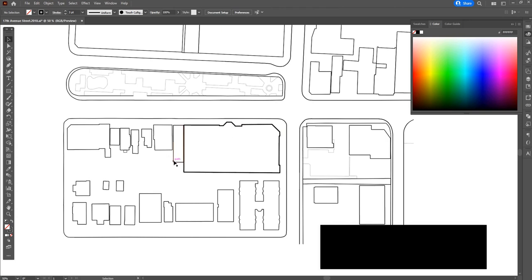As you can see, you can either go to the drop-down menu or you have the option to specify a number in the stroke weight command bar. We can type any number we like, 2, 2.5, 2.25. You can get as specific as you wish with your stroke weight. You'll get an opportunity to do some playing around with this, but as you can see, the fact that this is a complete and closed outline is the main reason why it's such a benefit to have all of these lines be closed polylines back in AutoCAD and before we import them.